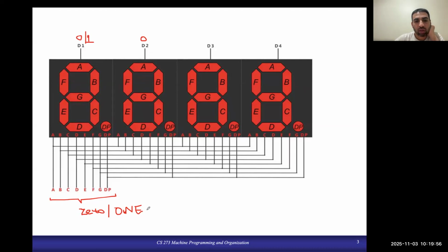And then I can put some wait. Again, I'm not writing anything here, this slash just indicates a wait. And after that wait, I can write here the code of, for example, 2. I can send in the code of 2 and set all other select lines equal to 1, and this select line equal to 0, d3 equal to 0. So now 2 will appear on digit 3.